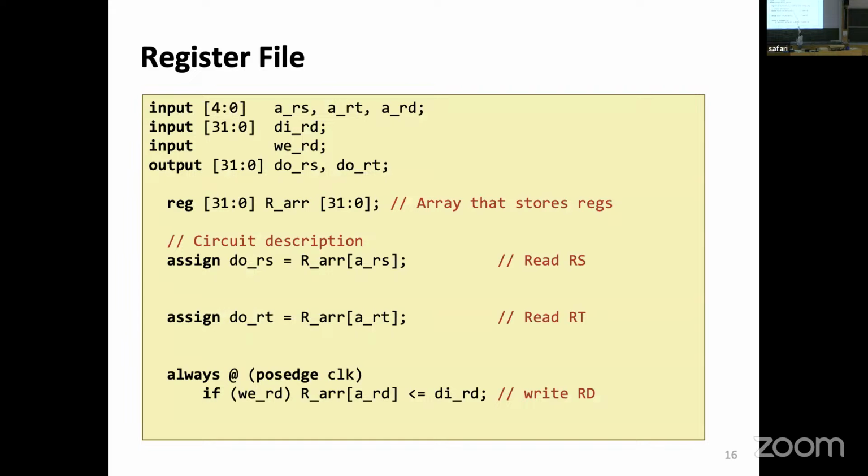And just to show you what this would correspond to in very low code, it looks like this. The entire thing is you have 32 registers, each one of them 32 bits. And I have 2 addresses. This address from this array picks me 1 output. This address from this array picks me another output. Notice this is combinational in this code. The moment there is an address, there is an output.